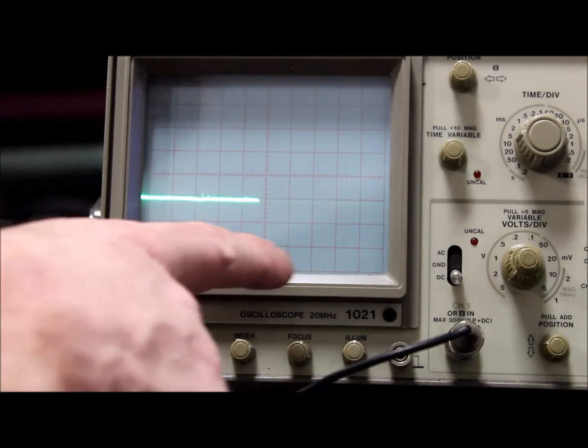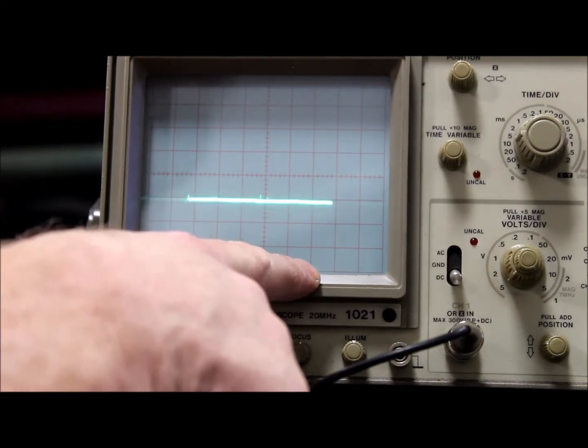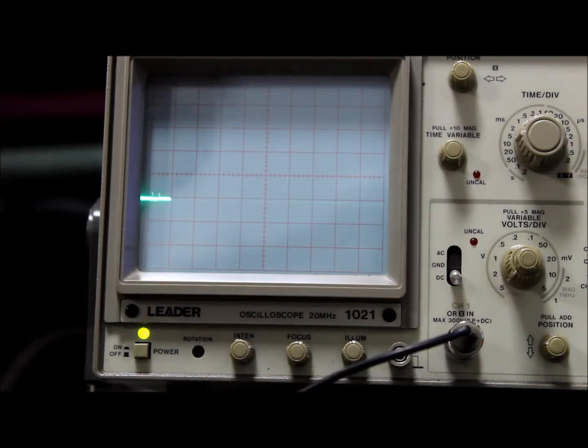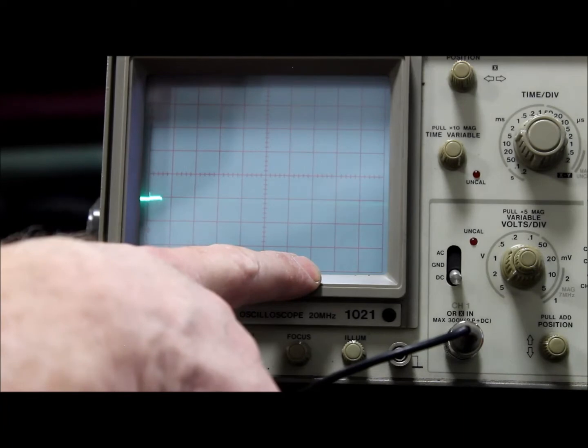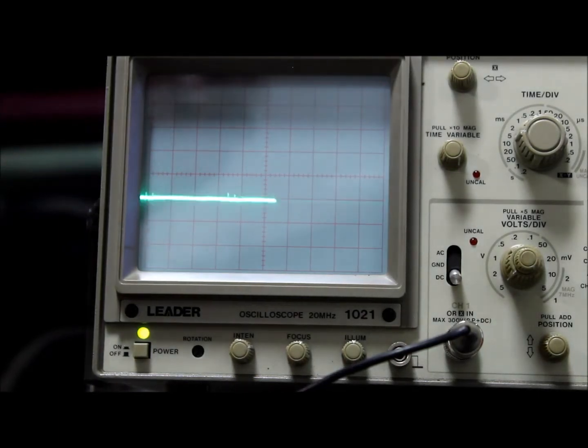What we're looking at for on time is when it's pulled down to 0 here. Kind of hard to get it to sit still because the engine RPM is not perfectly stable, but it is a little more than half a block, I think, and each block is 5 milliseconds. See if I can make it stand still a minute.